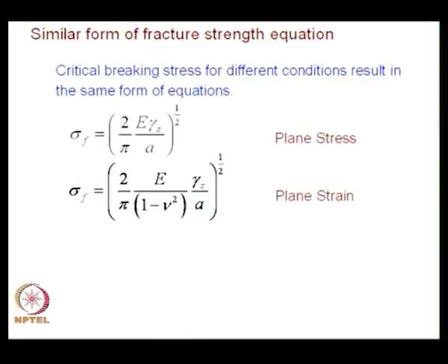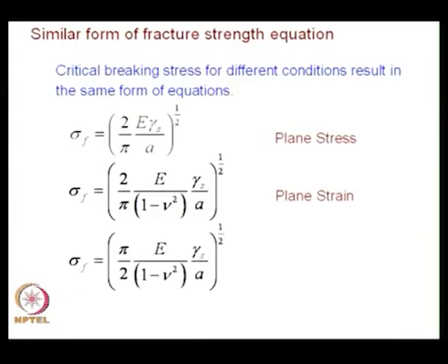And people have also looked at another problem, when you have a 3-dimensional solid where you have a penny shaped crack. The moment you have a penny shaped crack, people found the expression, only the numerical factor has changed, the form remained same. You have Young's modulus, you have surface energy divided by crack length, that remained same, only the numerical factor was changing.